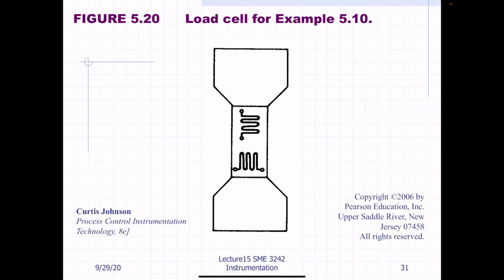This is the design for the load cell where we have a column. So we have two strain gauges here. Only this one is used to measure the strain because this is the strain gauge that is sensitive in the direction of the load. And this strain gauge here is not measuring any strain because it is in the direction that is insensitive to this load. The function of this strain gauge is as a dummy strain gauge. Later we will discuss the concept of the dummy strain gauge.